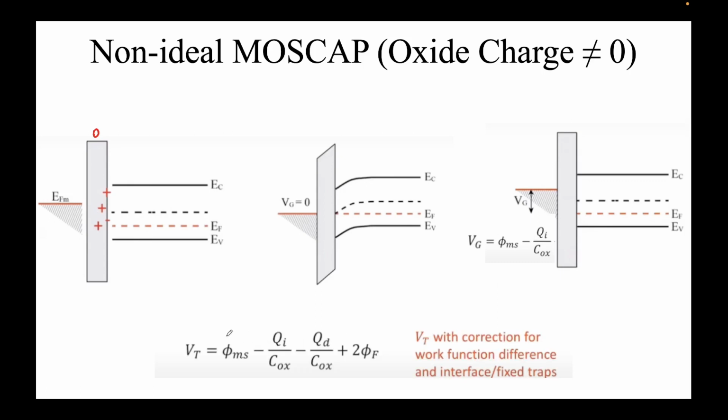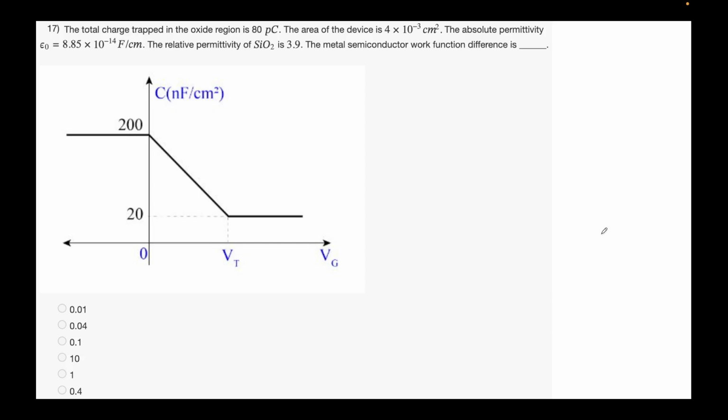And again, this is the VT. So this is your ideal VT, and you have offset by that amount. This voltage that we are applying to achieve the flat band condition is also known as flat band voltage. Very easy to remember name. It's named for its function.